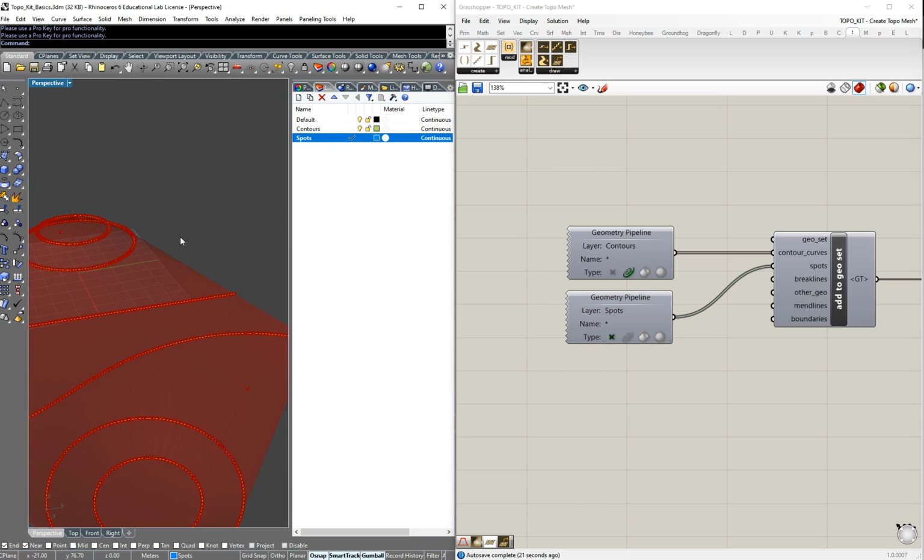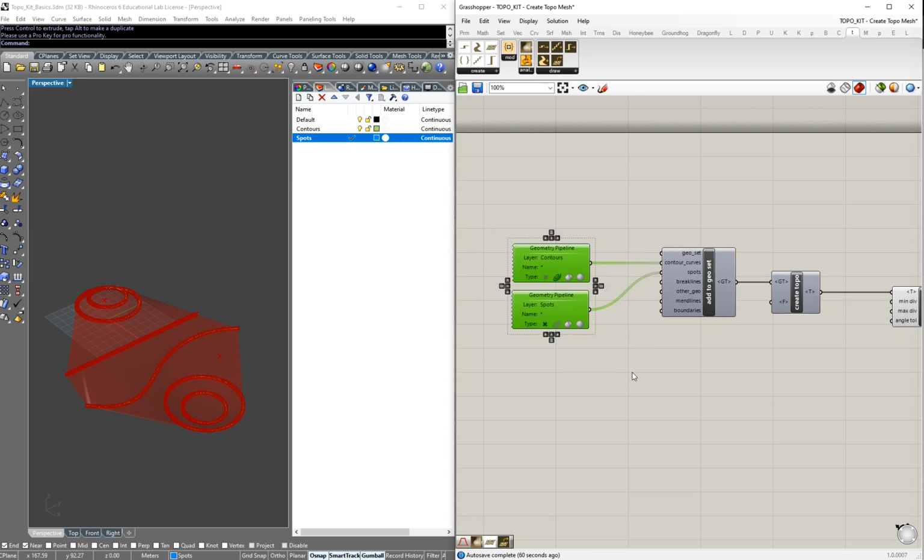Okay, so for example, in the future, I will show you in a video, you can bring LiDAR point clouds and import them as points, and then create the terrain from that rather than using contours, or you can derive contours from a DEM or a DSM, a digital surface model and digital elevation model. So here you have a quite versatile tool that you can modify and change by the height that you want. You can create multiple points and modify the terrain based on points and contours. So let's group this. We call it geometry input layers.